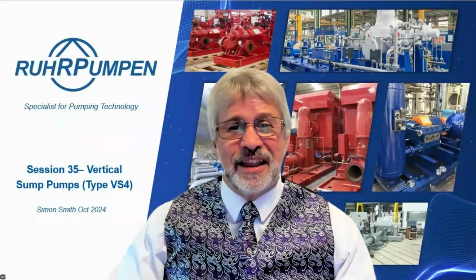Krishna Balusu says, is the steam jacket for molten sulfur pumps designed, fabricated, and tested to PED? Is it considered an ASME vessel? If you specify it, we'll design it that way. It wouldn't be normally because it's low pressure steam, but if that's what you want to specify, we'll make you an engineered version of it that would be to PED.